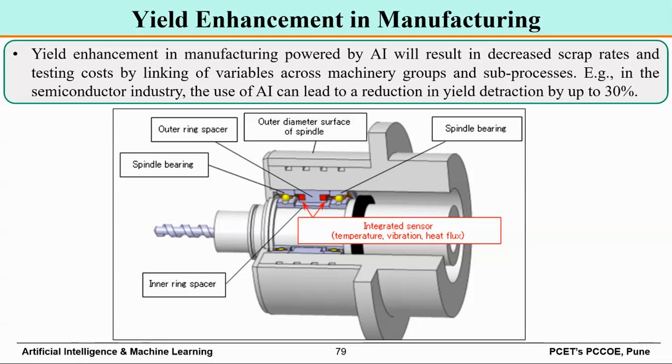Good. But consider a mass production system, so many machines are there, you cannot get that particular noise. Motion, speed. Speed will be there, speed will be achieved. But of course, this could be another feature. Because of the failure of the bearing, there may be a slight deviation in the speed, but it's very difficult to predict whether it is a failure of the bearing. Any other feature?